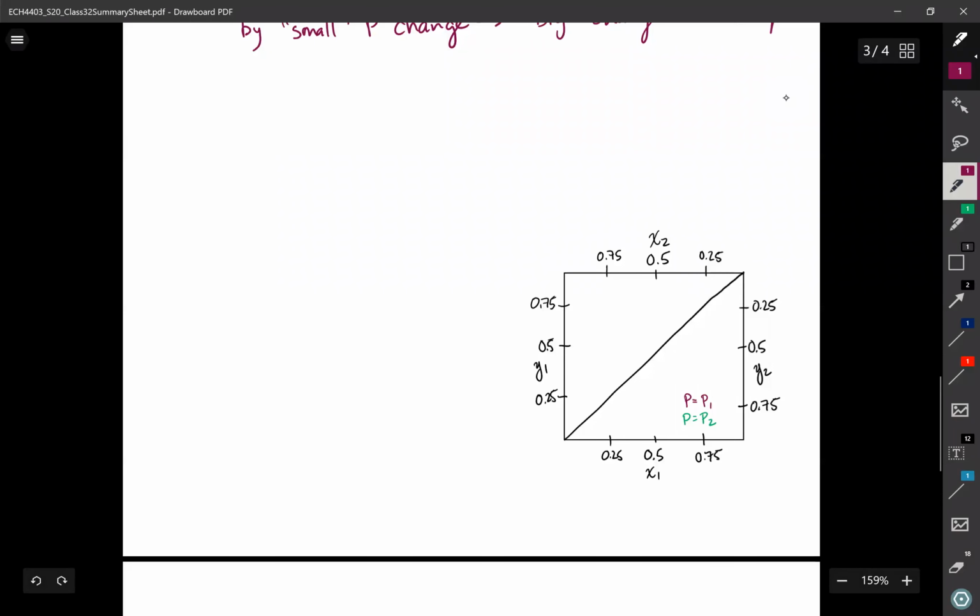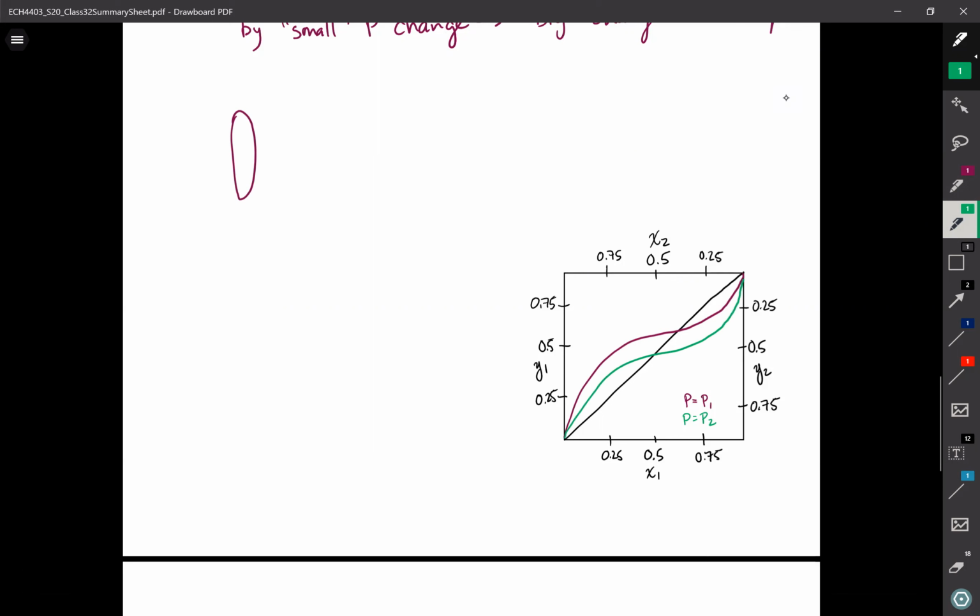So the general idea of a pressure swing distillation is just that it's two distillation columns that operate in series. And I'm going to refer to this equilibrium diagram as well. So let's just sketch in some azeotropic equilibrium data. Let's keep the same system from before, where P equal to P1 gives me an azeotrope that has a greater mole fraction than a second pressure, which we haven't really specified.